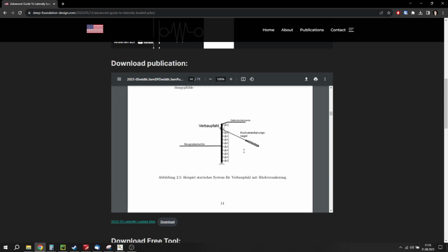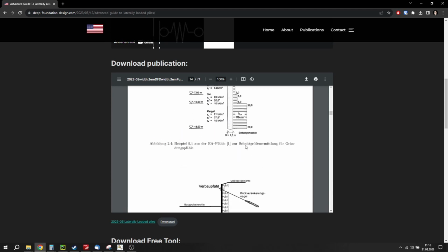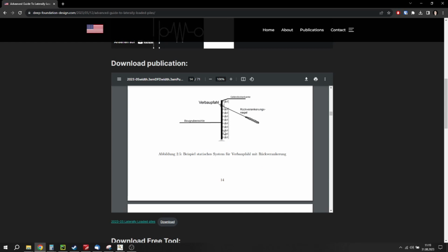have multi-layered soil even, but the problem is if we have a scenario that looks like this, where you have basically this would be like a pile wall, maybe you have an excavation and you want to secure the perimeter of the excavation with driven piles or with boring piles. Then the problem is you cannot use this very well in this more versatile situation, because you can obviously use this method for the lower part of the pile with a standard deformation at the top. You could use this even.